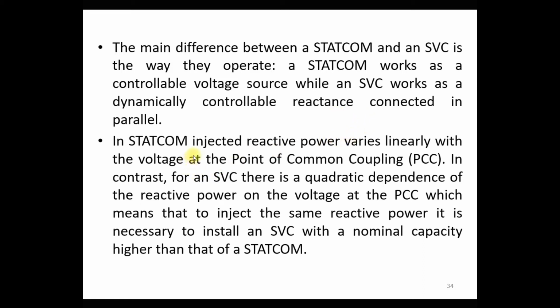So in the STATCOM, when you inject the reactive power, that varies linearly with the voltage at the point of common coupling. Whereas in the SVC, the injection of the reactive power is directly proportional to the square of the voltage, or it is a quadratic dependence of the reactive power on the voltage at the PCC.